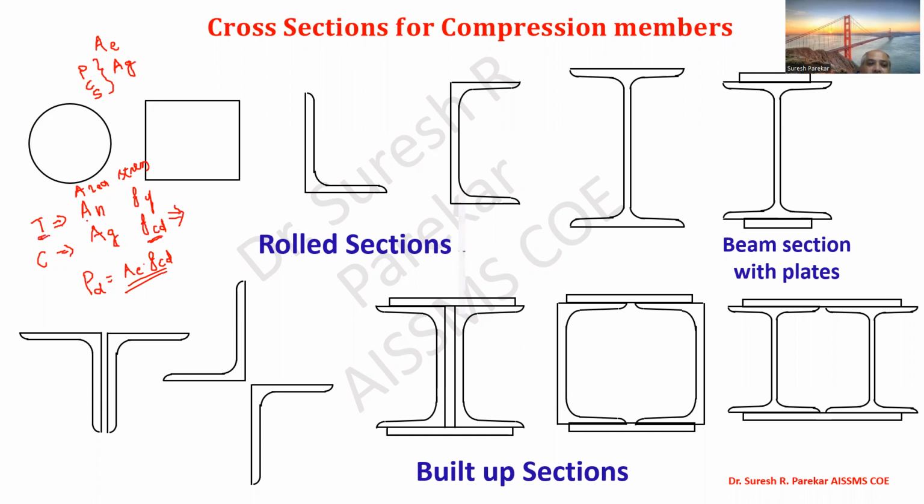For tension member we have to find net area, and for compression member, for these three, our area is the gross area of cross section. Now in tension member, for stress we consider the value of Fy, whereas in compression member we have to find the value of stress which depends upon L by R. L is effective length, R is radius of gyration, which we calculate as square root of I by A. So likewise, we should answer properly.